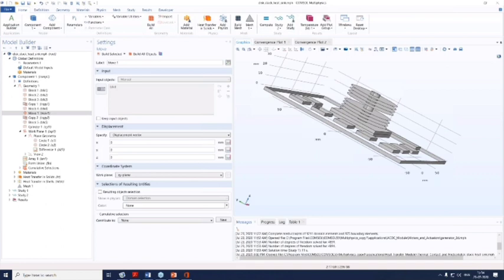Now, if the relative repair tolerance is 1e-3, in that case, the absolute tolerance is going to be 1e-3 times 10, that is 1e-2. And whatever the gaps, whatever the entities which are smaller than this particular tolerance, will be merged. And that's how this tolerance is calculated.